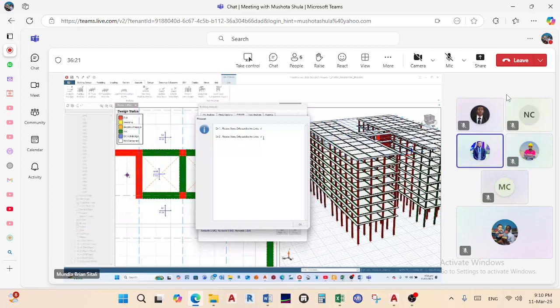It means we have sorted that out. In some cases, you don't even do your shear walls, but the columns are able to carry lateral loading. In some cases, okay. So you will have satisfiable story drifts in either direction.